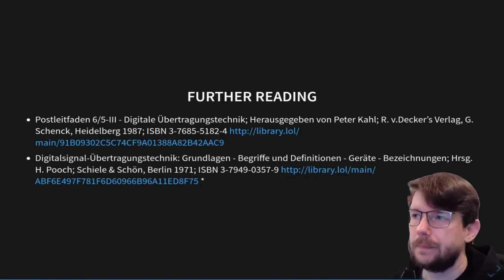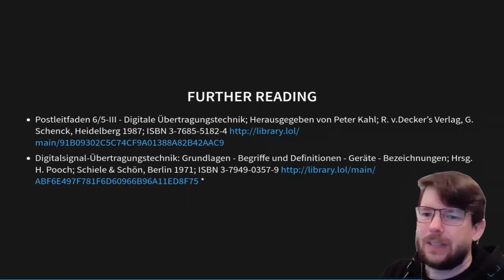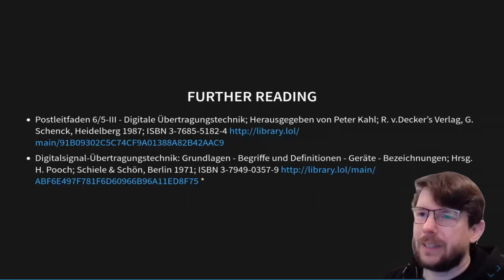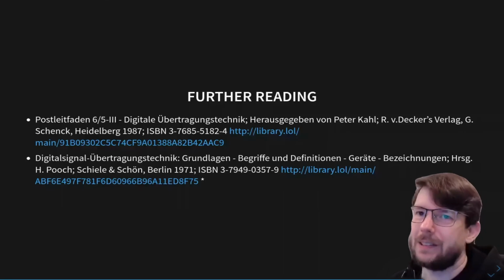I think that's actually the most complicated part, not so much the firmware, but the Osmo E1D client, because at the moment the API offers nothing to have any relationship between them. But for the client, I just wouldn't bother. I would just go for DAHDI. If you really want to terminate something like that, I would just implement it in the DAHDI driver, given that DAHDI already has infrastructure for all of this, and we can compare it with a Digium card. I think that's the easier way.